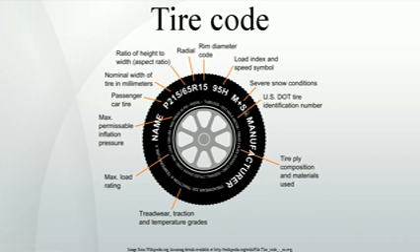Wheel rim widths. To determine the allowable range of rim widths for a specific tire size, the TRA yearbook or the manufacturer's guide should always be consulted for that specific tire. There is no rule of thumb. Running a tire on a rim size or type not approved by its manufacturer can result in tire failure and a loss of vehicle control.